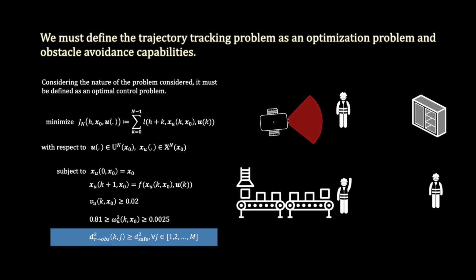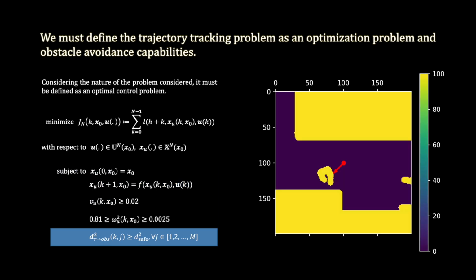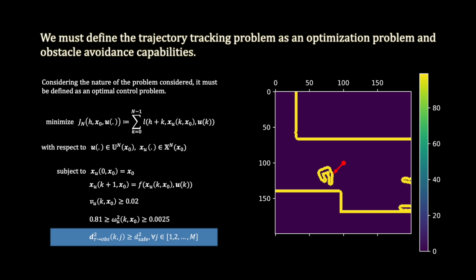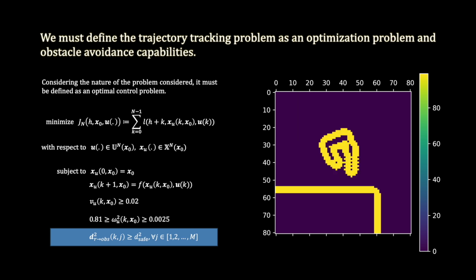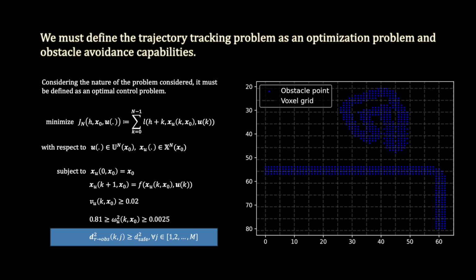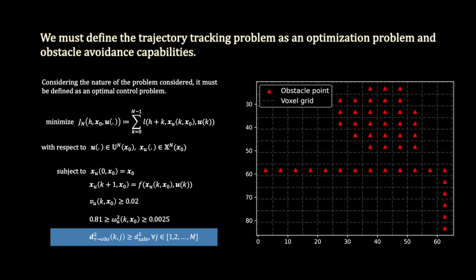When the robot scans its surroundings or environment, it creates an occupancy map, composed of cells with a value that represents the probability that that cell is occupied. This map is too large. It must be reduced. First, only the obstacle barriers are considered. Then, we can reduce the view window of the robot considering its heading angle, like so. Finally, the occupied cells are calculated as obstacle positions and bundled by overlaying a voxel grid. The voxel cell midpoints are now the obstacles, and the robot needs to keep a safety distance from each obstacle.